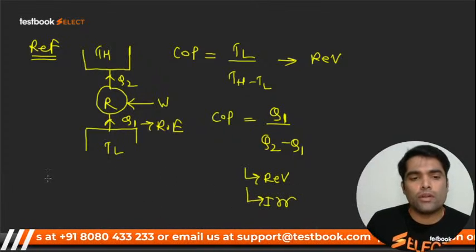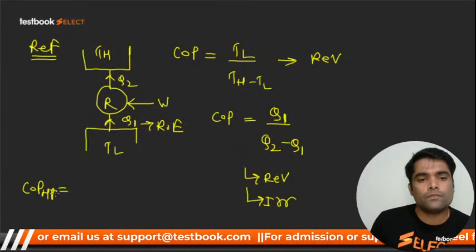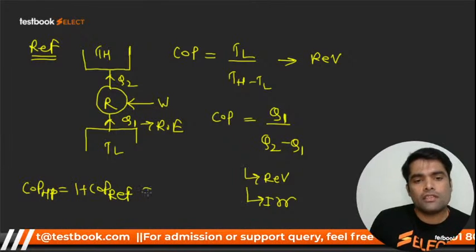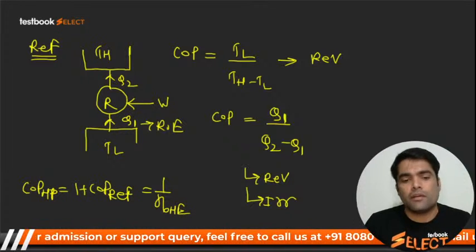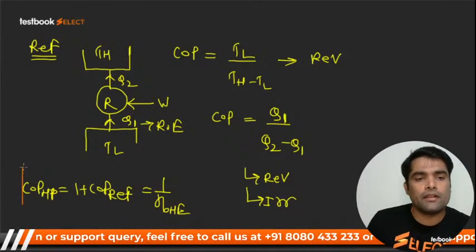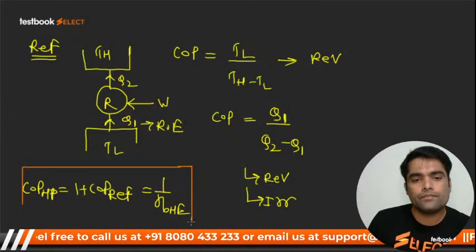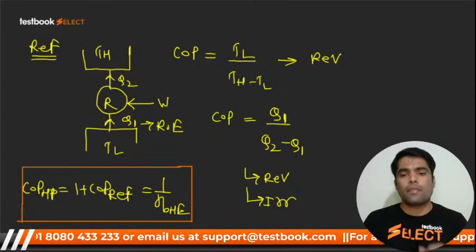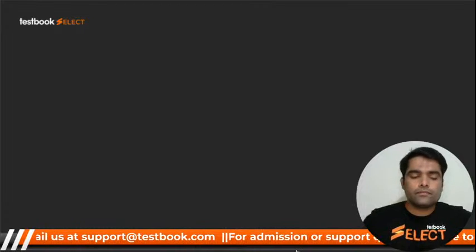And one more thing I want to tell you, that COP of heat pump is equal to 1 plus COP of refrigerator, which is equal to 1 upon efficiency of heat engine. This is the relationship between them. You have to keep this in mind. Remember one thing. Here we go for next.